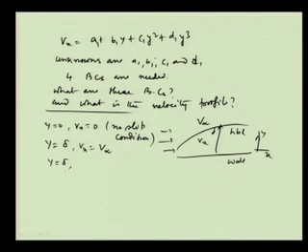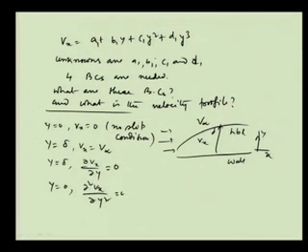The reason is there is no velocity gradient. So, V x is equal to V infinity. Therefore, we will write that del V x by del y will be equal to 0. Okay. And then what more? Another boundary condition. What is that? That is at y is equal to 0, again, we will write del square V x by del y square equals to 0. How?